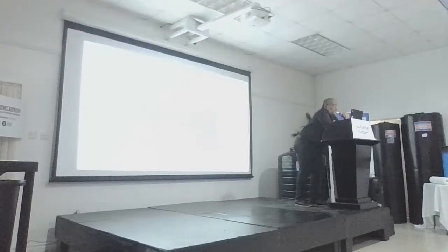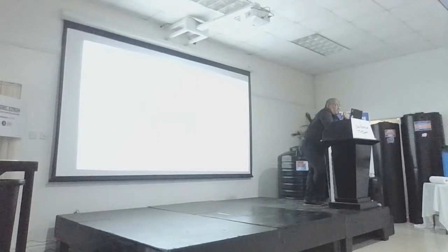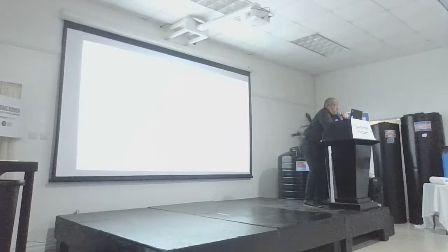So maintenance is important, and as I said, you should not run your gray water through the septic tank. Now I know there are some locations where they do it, but then you need to size the tank a lot bigger if you want to run both black water and gray water in it. The standard that we give you is based on toilet waste only. If you run gray water, then the capacity, the amount of doses, reduces, or you need to size the tank bigger to work with your gray water.